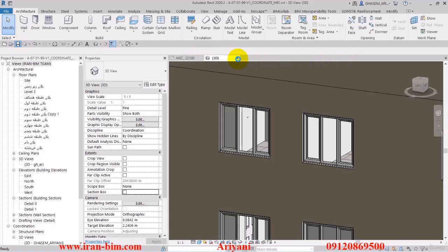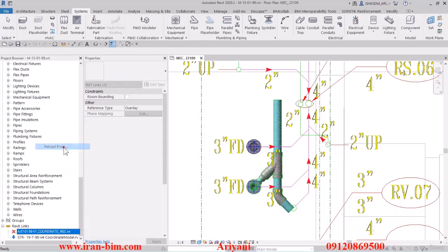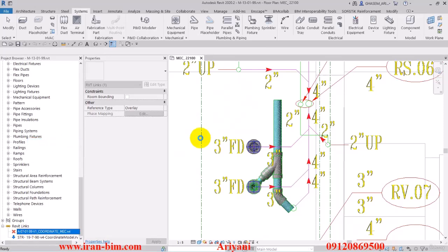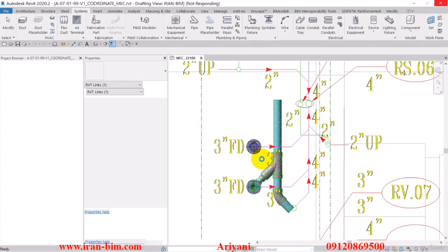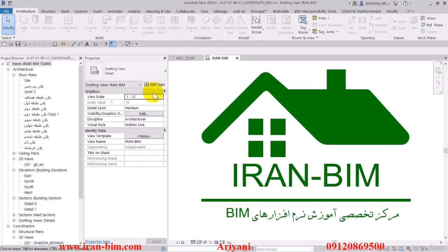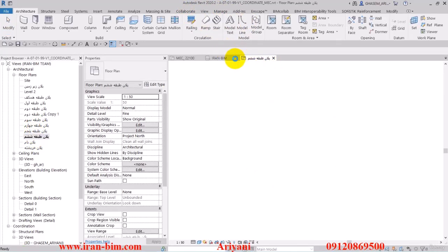So the final point is that when the architect is actually placing the furniture and you're actually working under a group designing program, what you should do is combine your architectural and mechanical furniture. For example, the sink that's used under the mechanical files should be used under the architectural ones as well. Now, how this helps us is it really speeds up the process of modeling and adjusting the details. Or even if the architect himself is placing the drain over here, they can attach a connector to it. If they use the same type of families, they will be using the same coordinates. And so everything is based on the same points.